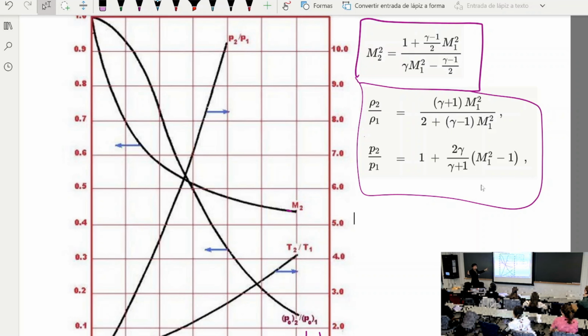Okay, if the shock wave is coming towards the stationary air, if you take a frame of reference that travels with the shock, then the stationary air is going towards the shock at the same speed as the speed of the shock relative to the ground. So you just need to figure out the speed of the upstream air relative to the shock, which is exactly what you said, right? You know the upstream temperature, you figure out the speed of sound, and from the pressure ratio you figure out the Mach number, you get the speed.